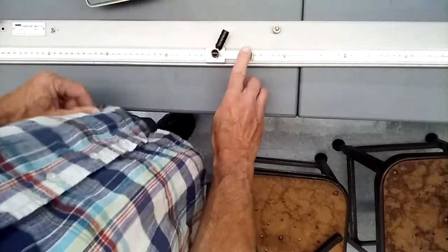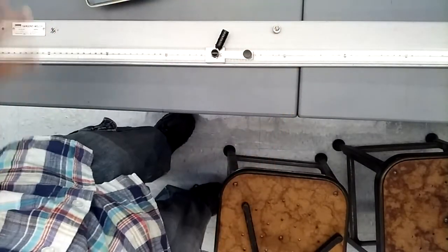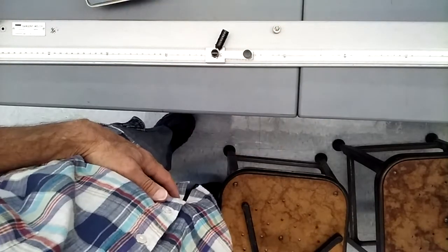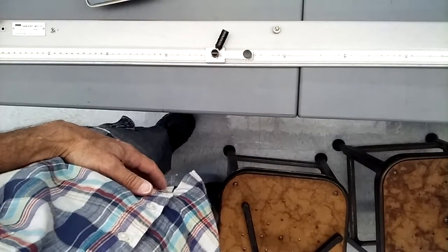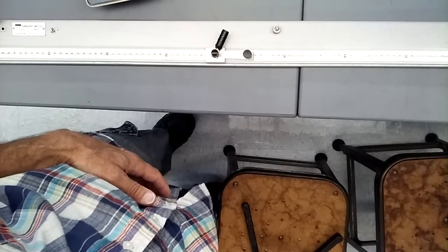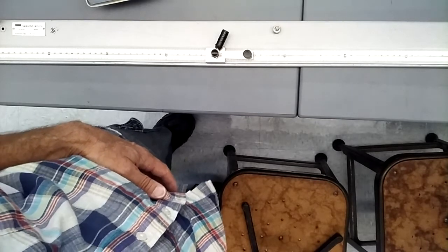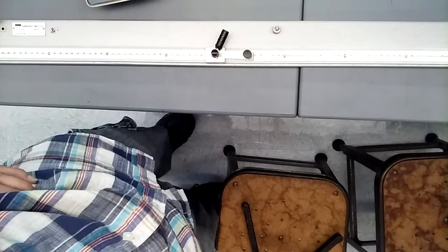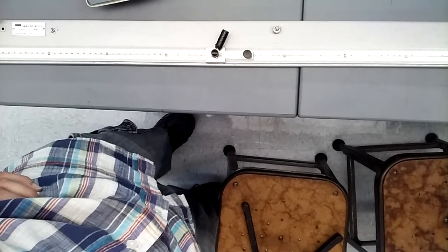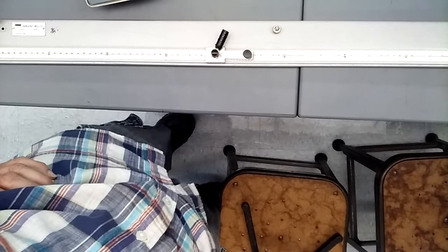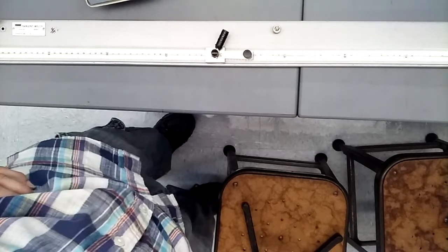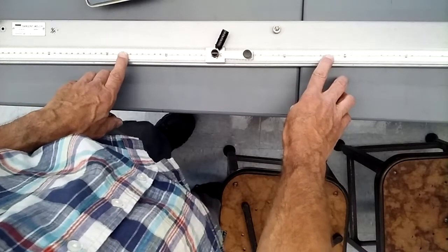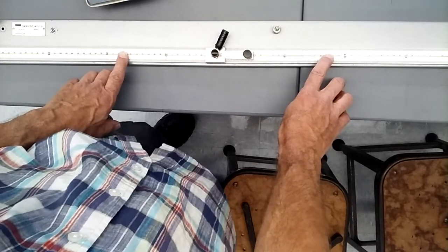Depending on wherever you have the contact set, one section of it will be R1 and the other section of it will be R2. Okay, so it turns out, that's why you might see written on the board, it might be up there, I'm not sure, but that formula Rx over R3 equals R1 over R2, we could also just as well use L1 over L2 in place of R1 over R2. We don't really care about the resistance of these. We just need the length will work for us.